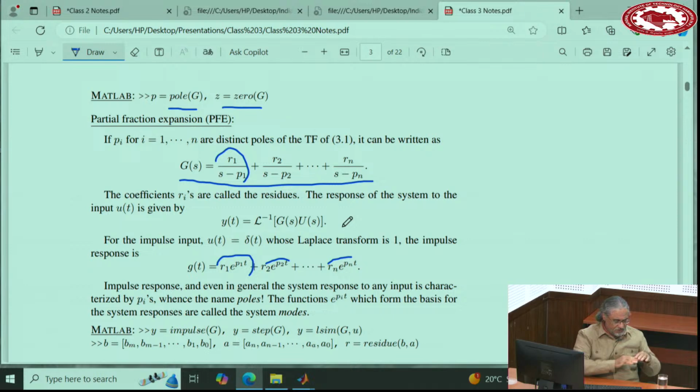If the response of a system can remain bounded, we say this system is stable. If they grow and go to infinity, we say this system is unstable. So immediately you see the condition. We can mathematically prove all the details, but it's not necessary. The condition is all the poles must be on the left side of the complex plane. If they have that condition, the outputs of this system remain bounded for every bounded input. So as long as the input is bounded, the output is also bounded.